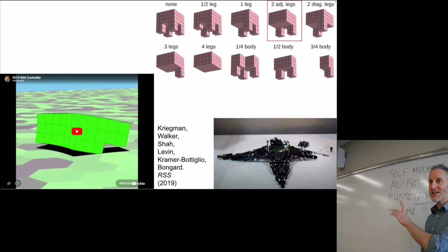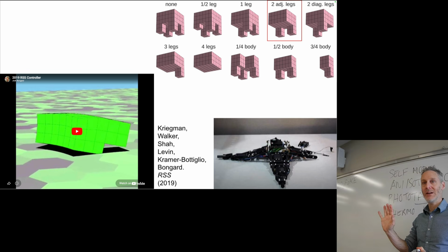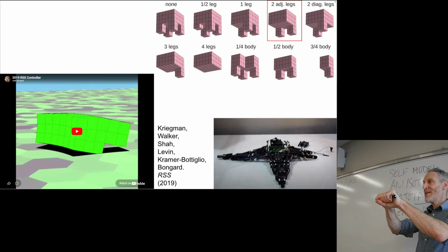So the voxels, which you're going to see, remember, are a bit of an illusion. This is just for the visualization. So underneath are the beams. What's the connection from the controller to the beam? It changes the equilibrium length of those beams, so it can shorten it and make it have a stronger pull, or extend it and make it a stronger push. Absolutely. So every beam in the soft robot you're about to see, and every beam in Nick Cheney's experiment that you saw before, at least the red-green voxels, which were the ones that were actuated, there is a motor neuron from the controller attached to that beam.